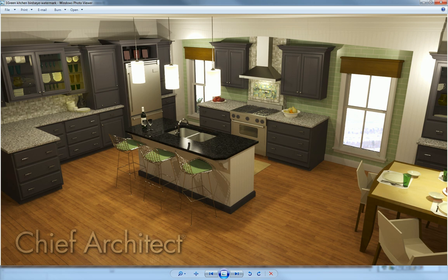The fastest and quickest is what you've seen so far, and it's actually a pretty impressive render view. Then from there you can go to a final view with shadow, and then we have a ray trace view, and that's what you're seeing on your screen right now. Our ray trace will look at complex lighting situations, and it will calculate how light will reflect off of surfaces, whether they're shiny or matte finish, and how shadows are cast and softening of shadows.